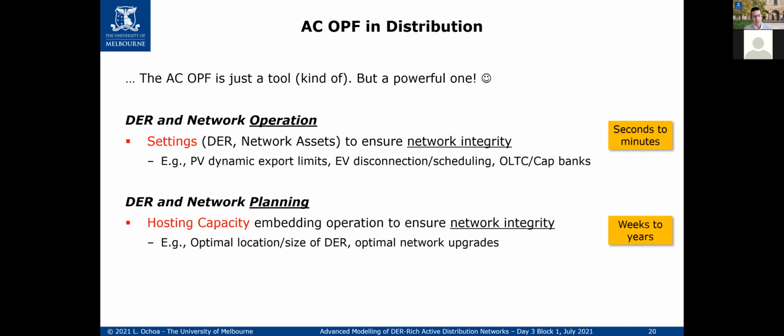And of course, in this case, if it is planning, we can always look at the critical worst case scenario, well, worst case scenario is critical by definition. For instance, if we're looking at generation, it would be the maximum generation and minimum demand. So if we're looking at a solar PV farm, it would be at midday, all right? So what is the demand? And then you just optimize your problem, and then you find how much you can inject. And that's it, worst case scenario.